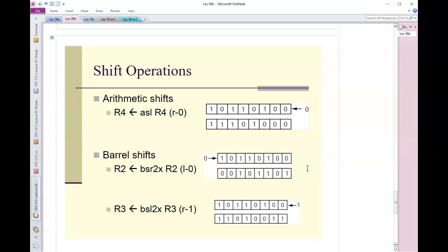So there's two types of shift operations, just simple shifts as we noticed them before, but there's also, we'll say, barrel shifts. A typical shift operator, under our shift register, is understood to shift one bit at a time, but we don't really need to do that. We can actually shift multiple bits. So if I'm shifting multiple bits on the same clock cycle, it's referred to as a barrel shift. And it turns out the shift operators in RISC-V are actually barrel shifts.